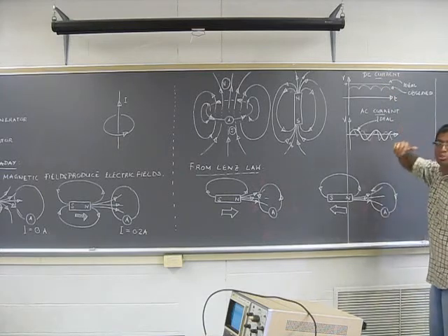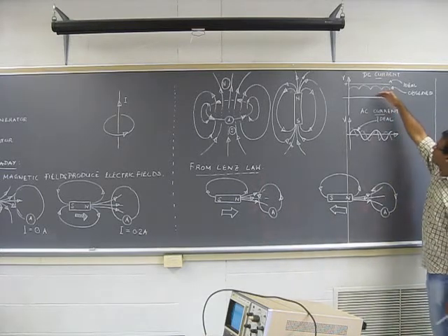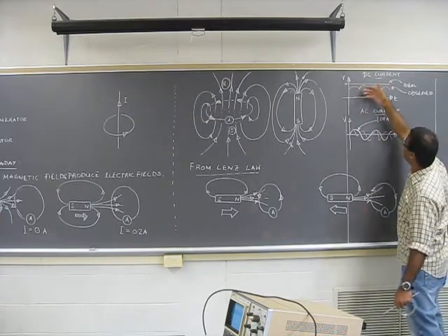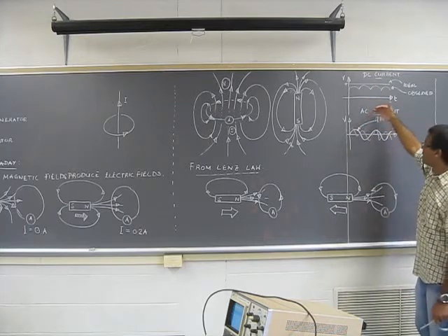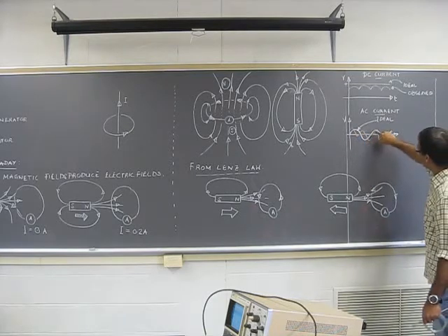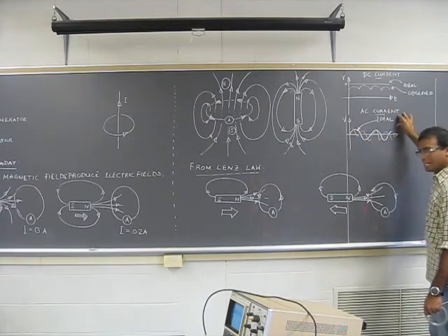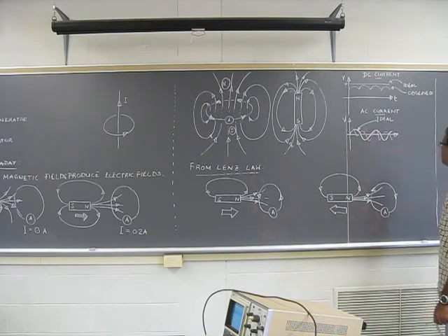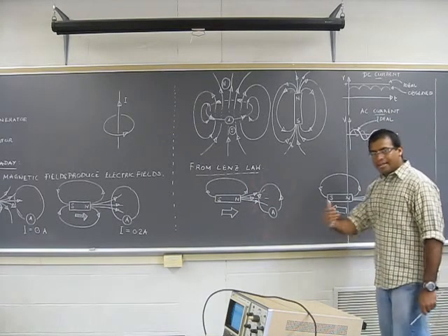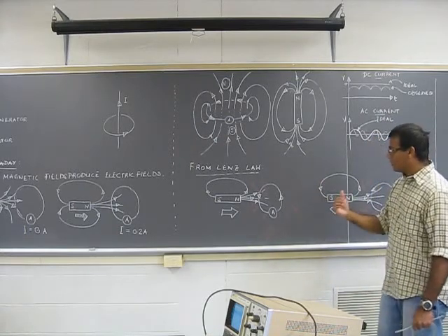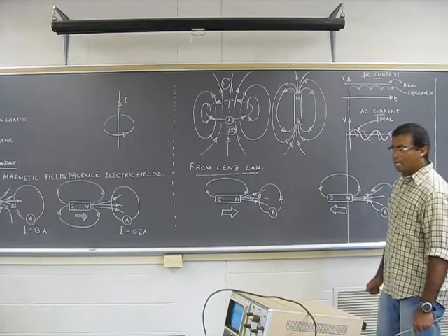That is because it's not a smooth generator. Another thing is that when you rotate the generator in the opposite direction, you will see that this pattern will flip sides. That will be another indication this is a DC generator. Now, for the AC, you will have a nice sinusoidal curve in an ideal scenario. But in our case, we will have a jagged, kind of rough waveform. This is what you're going to observe. I did this part as an added part to the first because, unfortunately, the first part of this got cut off.